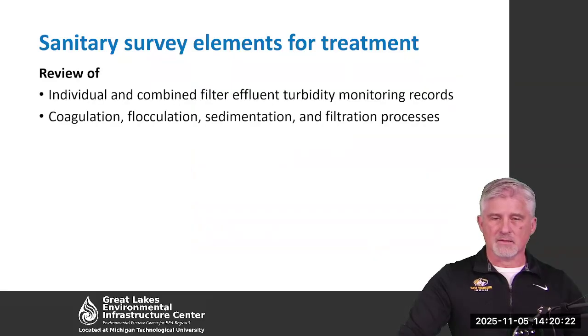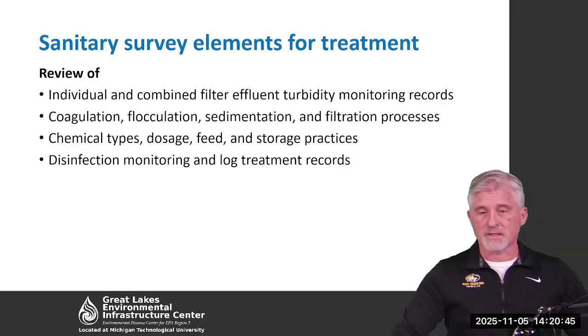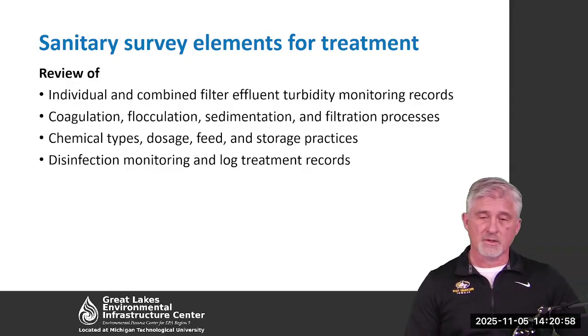What are they going to look at when they come out? Well, they're going to look at your individual and combined filter effluent turbidity monitoring records. They're going to look at your treatment train: your coagulation, flocculation, sedimentation, and filtration processes. They're going to look at what different chemicals you utilize, and are they NSF approved? What are your dosages? How are you going about feeding them? What's the pump you're using? How do you store those chemicals? Are they properly stored?